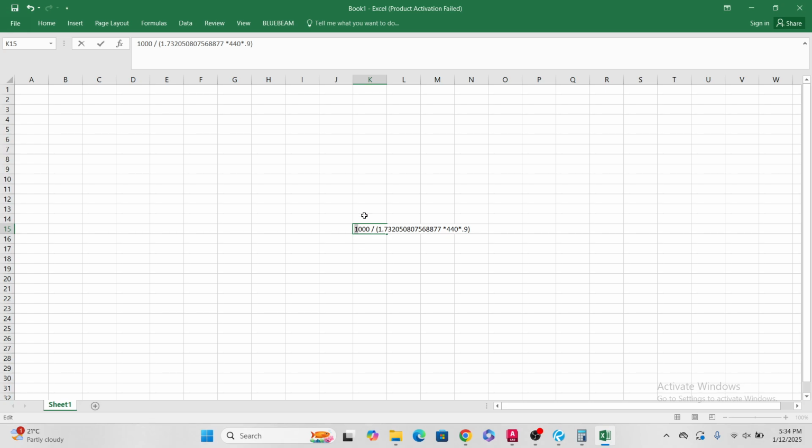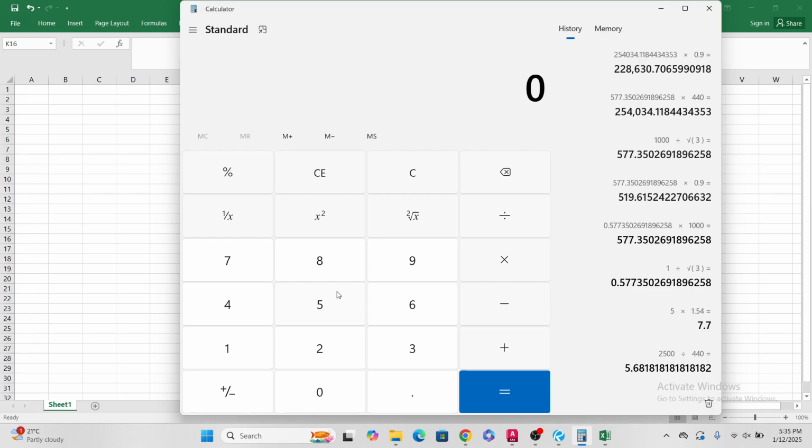I think I pressed something. Equal. Enter, 1.45. So if you go for power factor 0.8, it will be 1.64. It's like that. So I'll go with the 0.9. So it's 1.45. So I have, let's say, 4.5 kilowatts into 1.46.